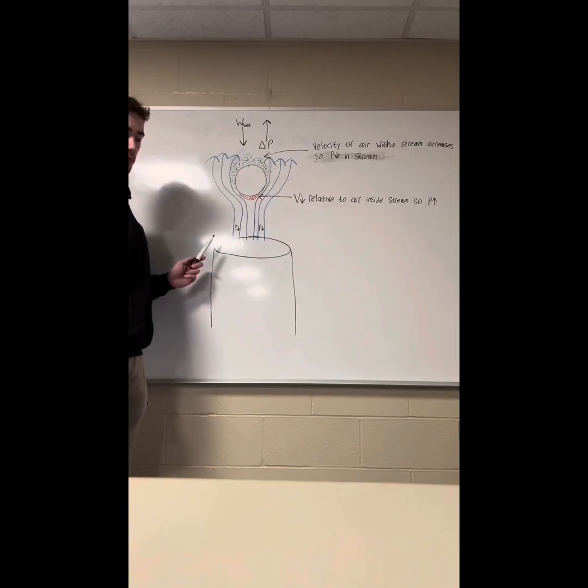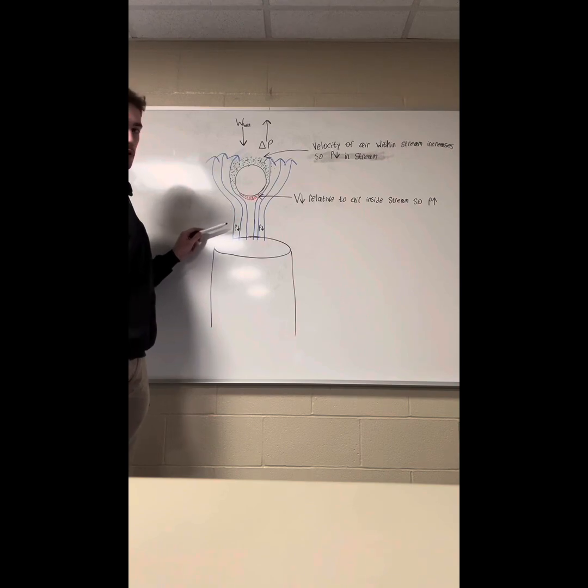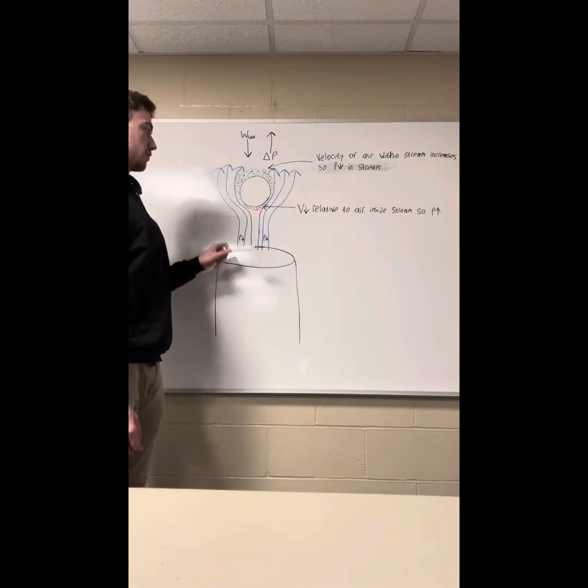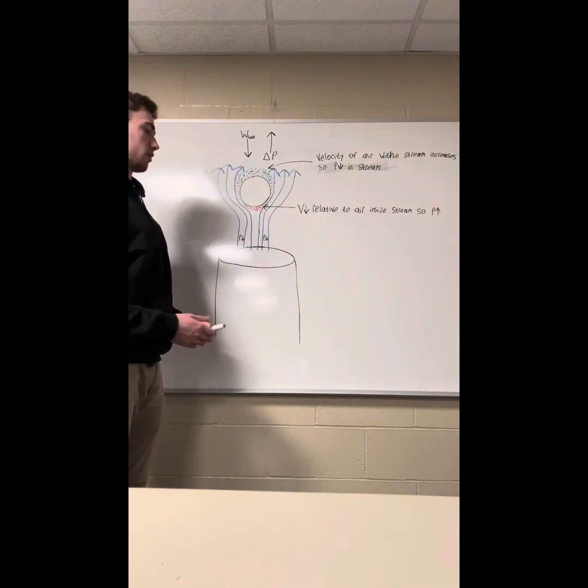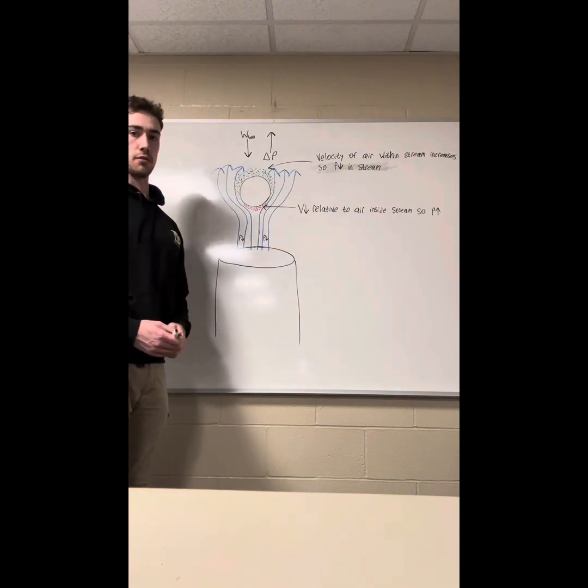When the hairdryer blows air, it increases its velocity, creating an area of lower pressure within the airstream. But when the air comes in contact with the bottom of the ball, its velocity must decrease due to friction, creating an area of higher pressure underneath the ball compared to the rest of the airstream. This pressure difference between the bottom and top of the ball counteracts the force of the ball's weight.